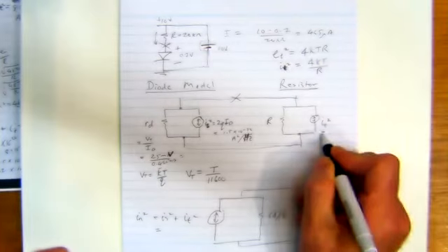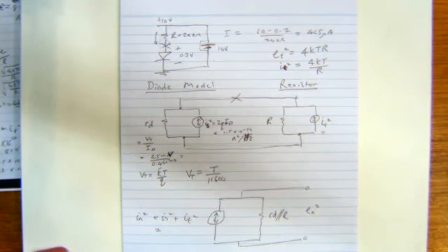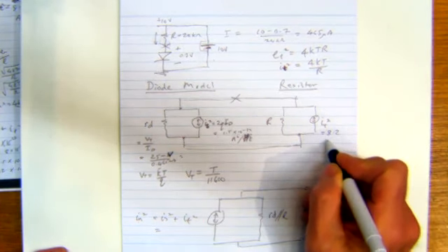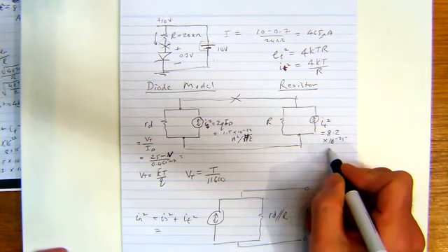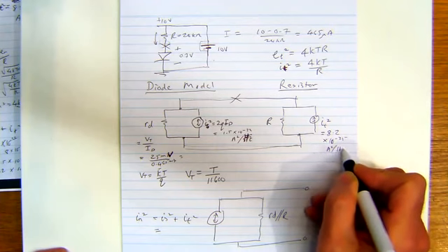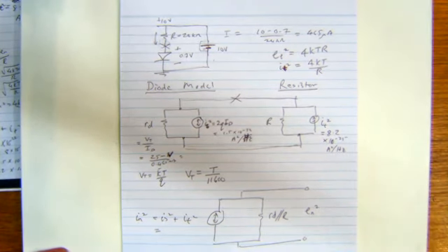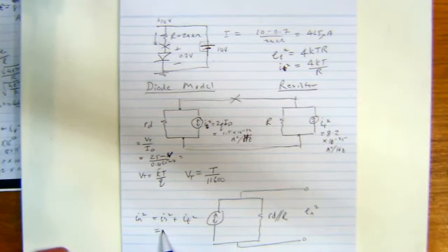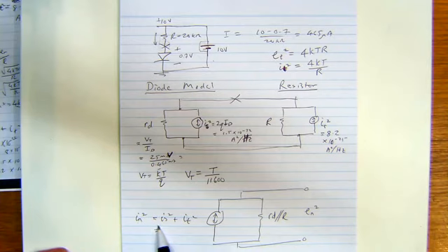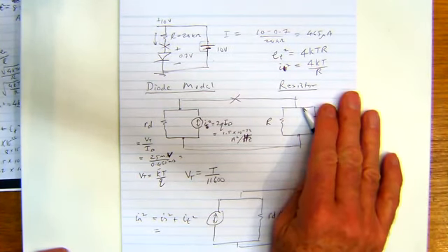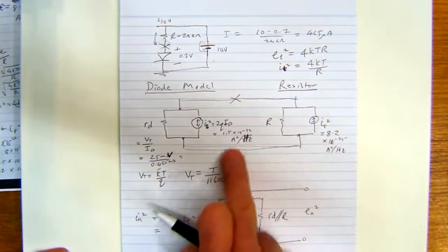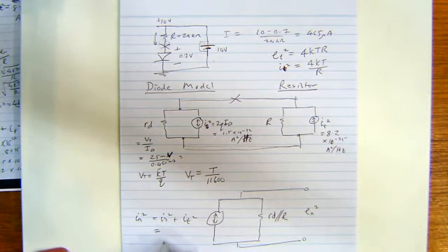And what about this one over here? Anybody got that thermal noise? 8.2? Okay. And the units are amp squared per hertz. Yep. Alright, so when it comes to this bit here, would I be in trouble if I just neglected that? If we just drop that and we just say it's mostly the shot noise? Yeah?